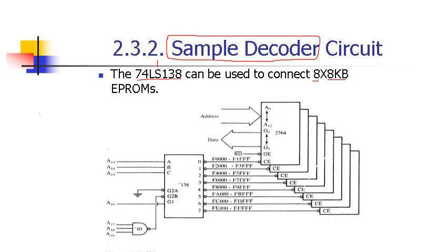From your microprocessor, you are bringing in an address of 20 bits. Each of these chips requires only 13 bits. So we take A0 through A12 from these 20 bits and connect them to your first chip. To get the data from the beginning address of the first chip, we first have to select this chip.